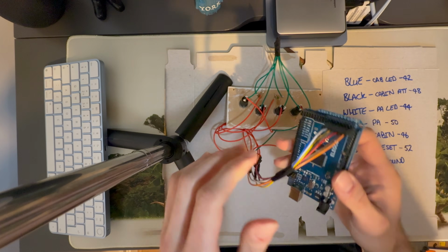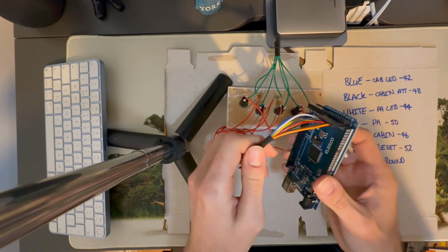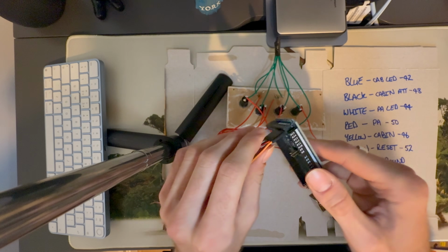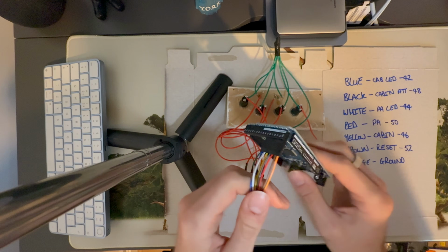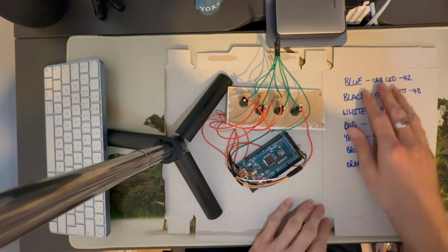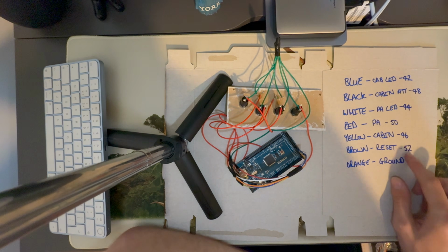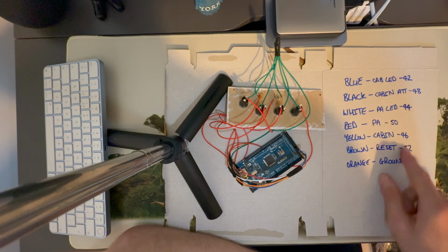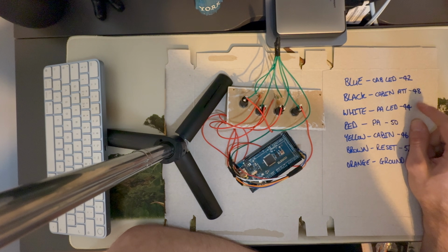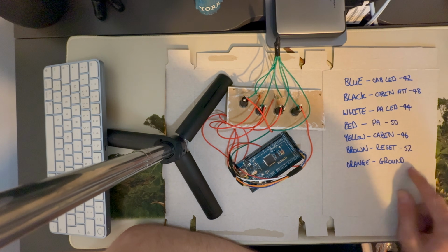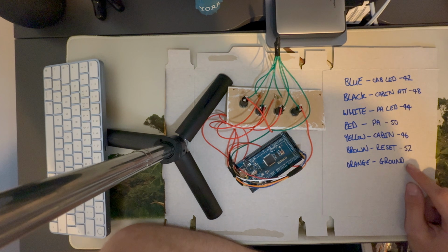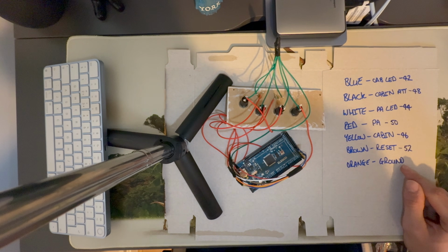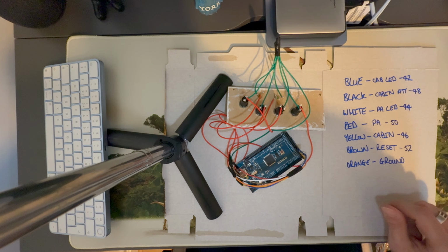All the magic's done through this board. I've added some electrical tape, as I said I would, just to keep it A, tidy, and B, secure in place. And as you can see here, I've got all the inputs, so these are important. We're going to use these in a minute in Mobiflight to configure it and program it to work with the Phoenix. Don't need to use the pin for the ground because it is just a ground connection, a negative. We don't need to do anything for that in Mobiflight, so we're just going to leave that as is.